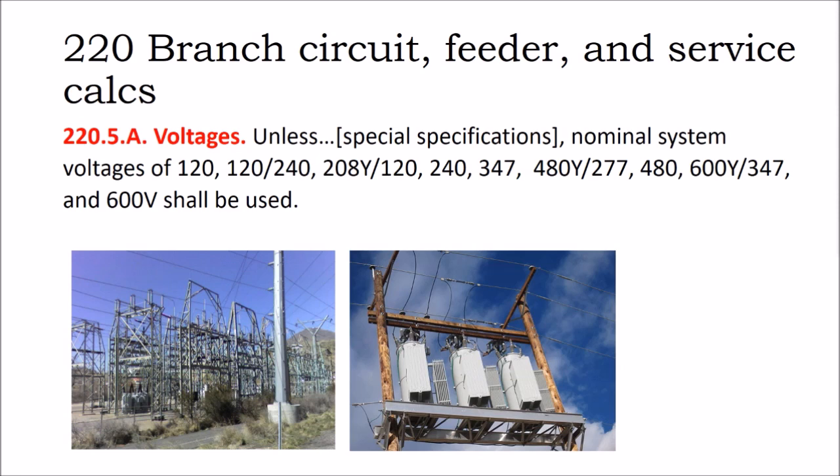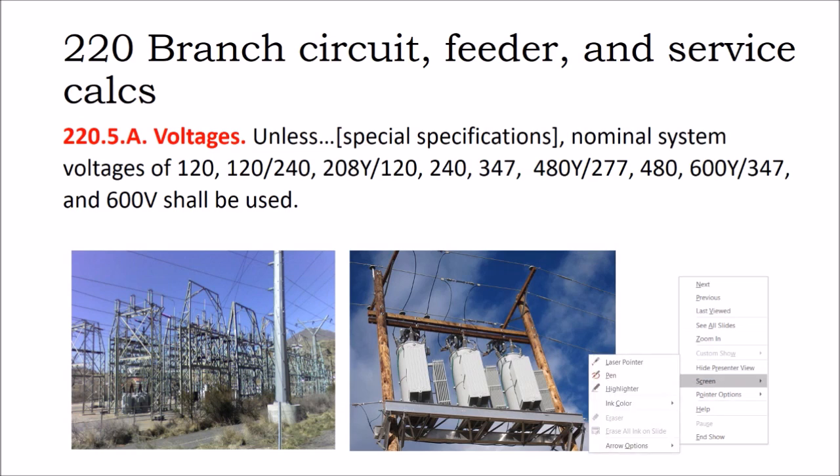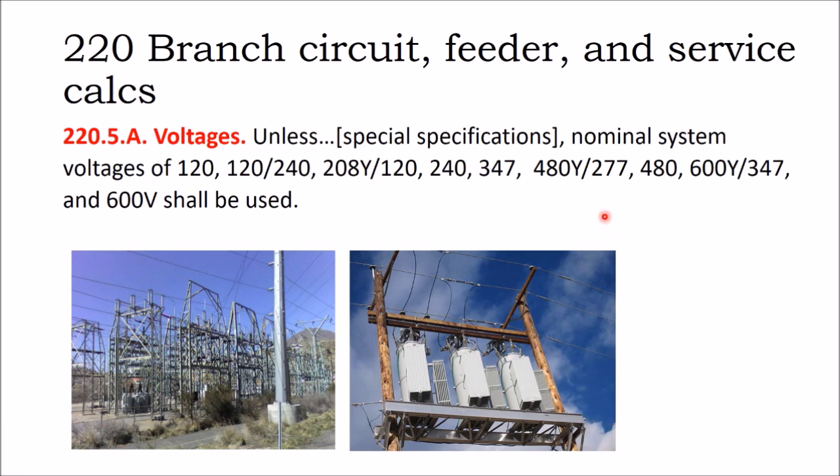When you get into commercial design, if you're picking out what kind of transformer to use, and you're choosing to hang a transformer on the power line, you might have a choice: do you want to do 208 or 480Y? Typically you'll opt for 480Y simply because by having twice the voltage you have half the amperage, and so you get more bang for your buck in terms of conductor sizing at a higher voltage. In fact, the longer you transfer electricity, the higher in voltage you want things to go.